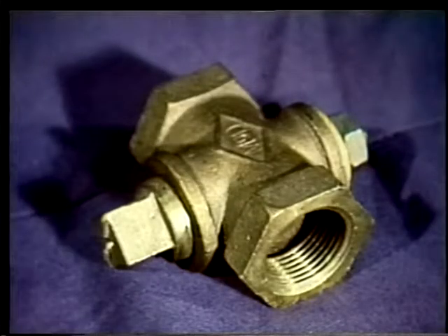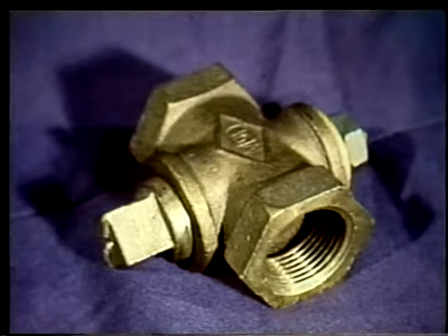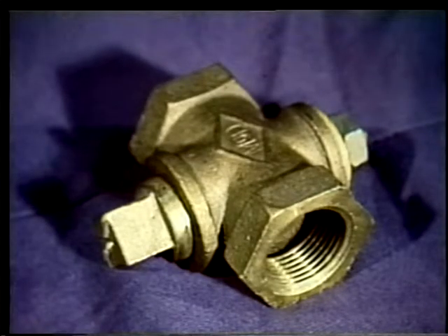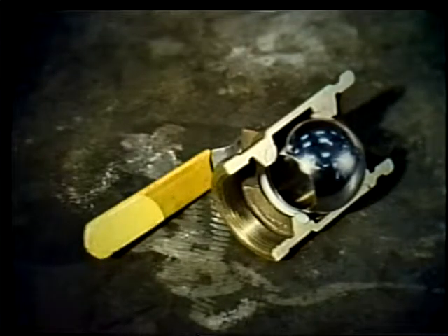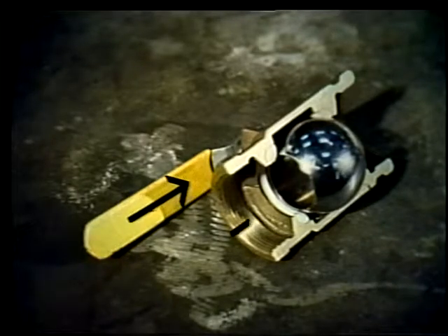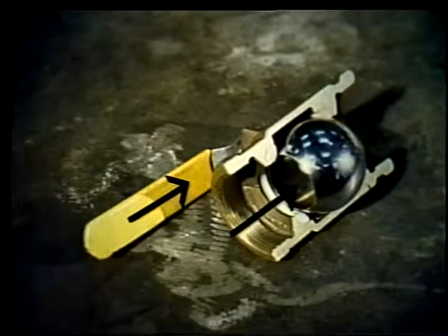The plug valve is very adaptable to systems carrying slurry. Slurry is a fluid often containing large particles. Often the valve will indicate which way the flow is going. For instance, on duplex strainers, the handle will point to the strainer with the flow through it. In a regular on-off ball or plug valve, the handle is usually in line with the port. So if the handle is lined up with the pipe, there will be flow through it.